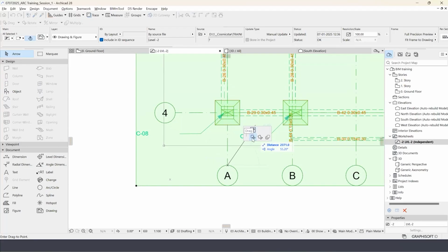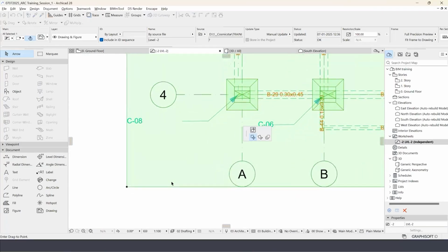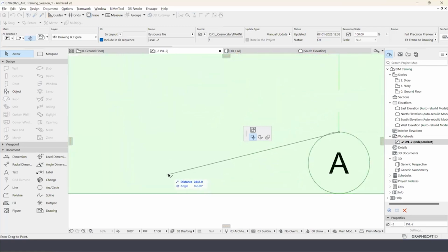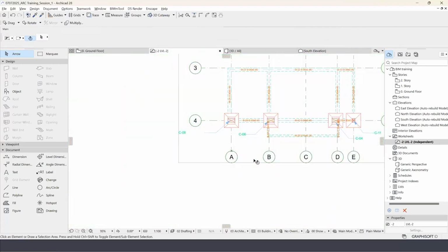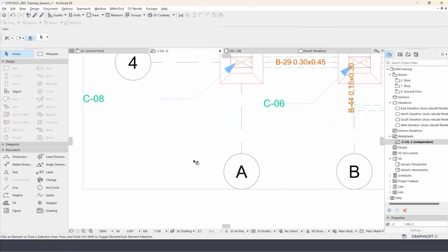But if you see something like move, it might be looking at a very specific part. Don't worry about it right now. We will go into these tools soon. But make sure that you're using the drag option here and move it. I'm not doing a click and drag. I just did one click, left the mouse, and I'm just moving it, placing it to the point. Something I want you to check here is when I go close to this point, you can see my cursor changes to a tick symbol. That actually means that it is snapping there. So when I click there, it will be moved. There are also commands which we will see soon, but I'm just making sure I place it in the right location. This is not the ideal method.